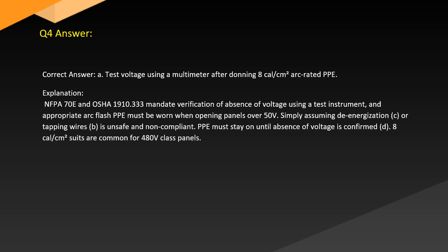PPE stays on until absence of voltage is confirmed. D. 8 cal/cm² suits are common for 480 volt class panels.